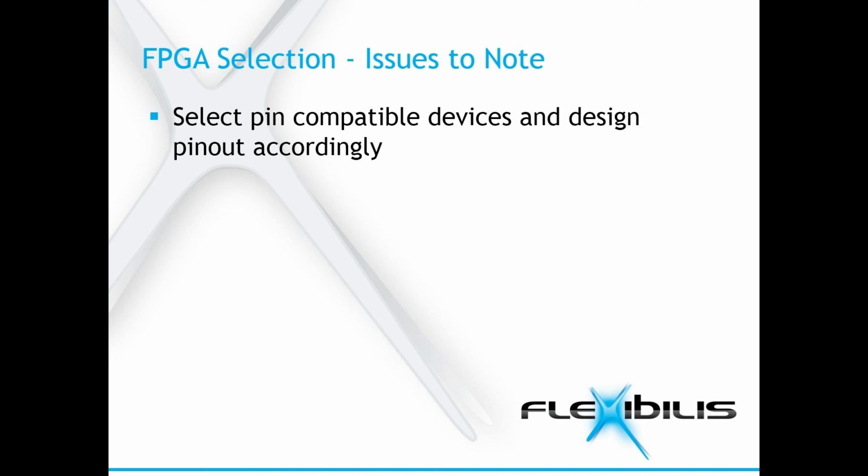Select pin-compatible devices and design the pinout so that you use only the I/O that is available in all the devices you might change later to. The Quartus tool provides assistance with this.